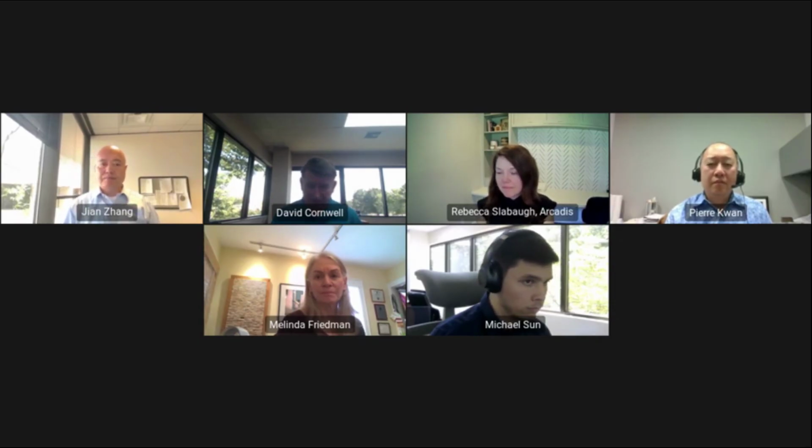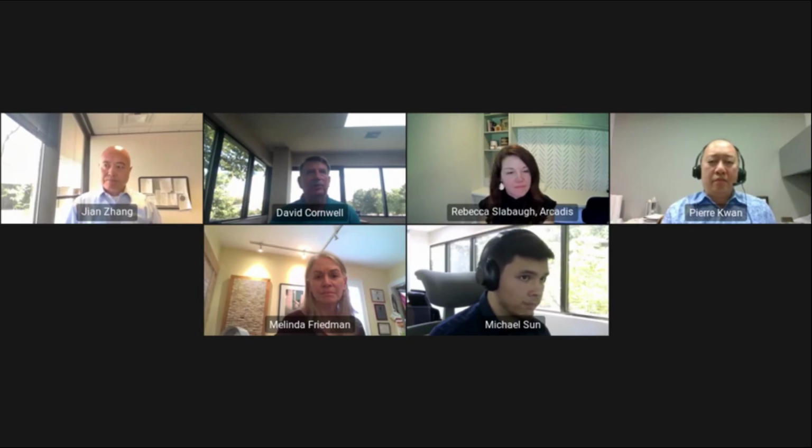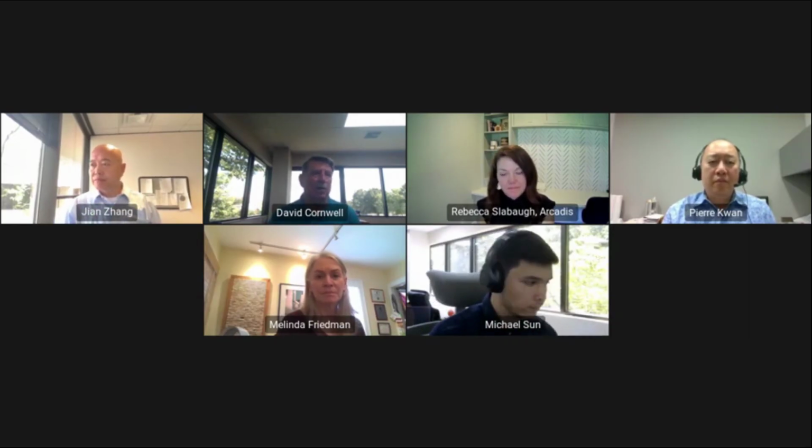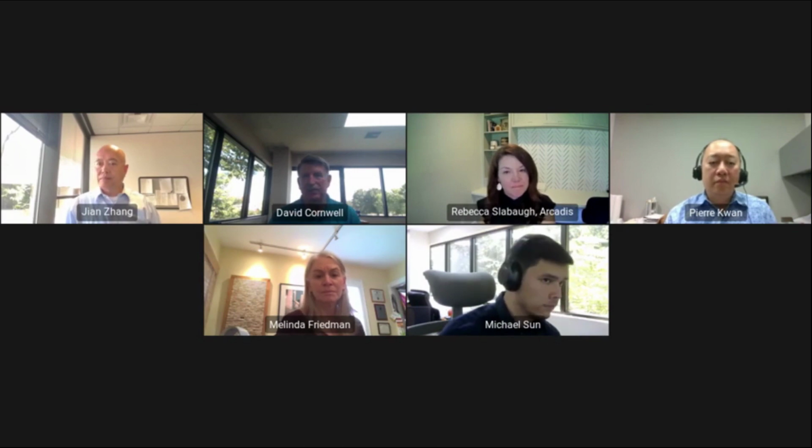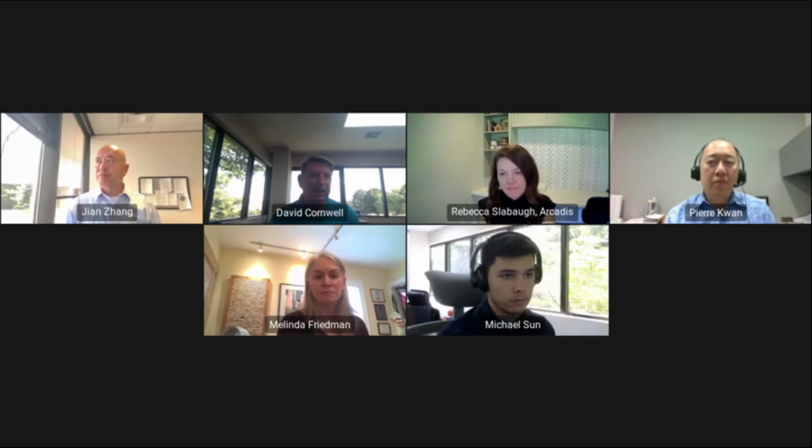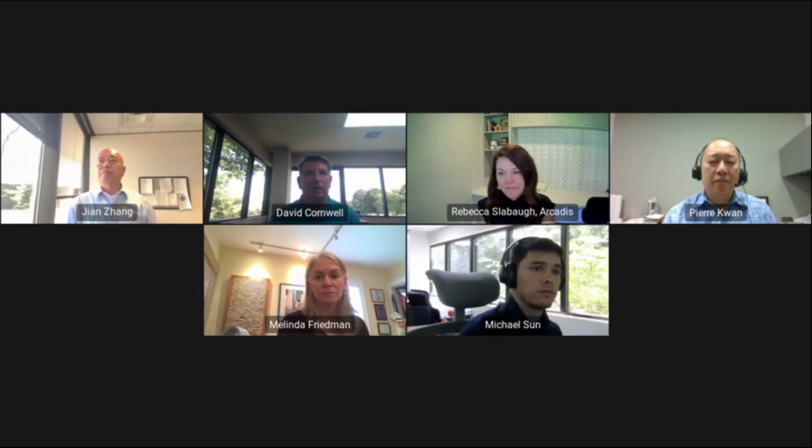Okay, thanks, Jan. That's a good question. Certainly, most of these are done at the water treatment plant, but what you want to make sure you do is look at the difference in your key water quality parameters at the plant and in the distribution system, right? Because often at the water plant, you have much different conditions than in the system. A simple case might be I'm going to use orthophosphate and my water plant pH is 7.8. In the distribution system, it's 7.4. Say, hey, that's all in the right range. If that's the only thing I see different, I can do it all at the water plant.